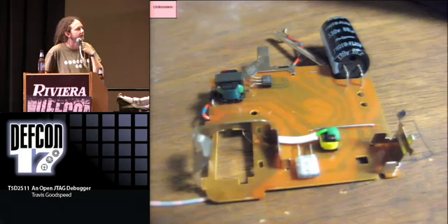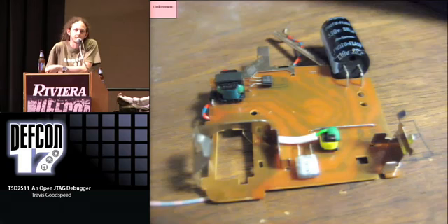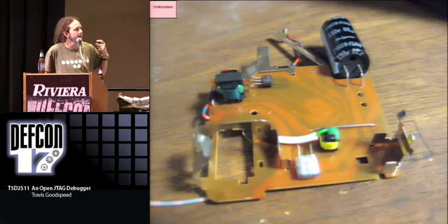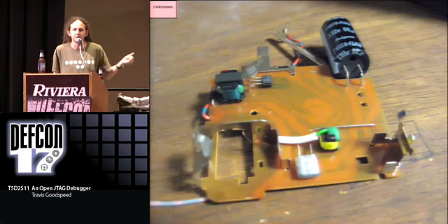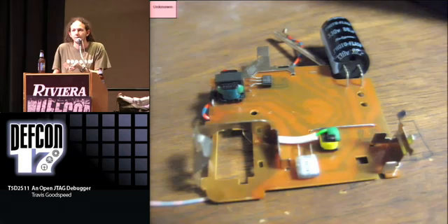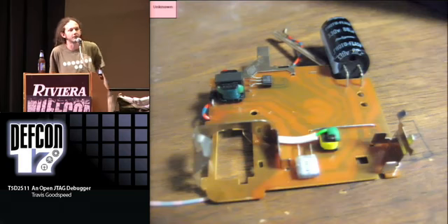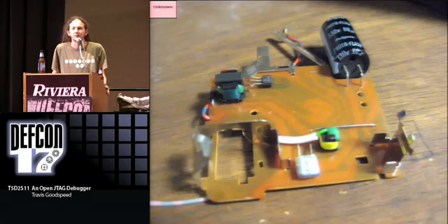But it stands to reason that if you could burn out the input and output pins of the JTAG state machine, then when an attacker tries to break into the chip through JTAG, he'll have no way to communicate with it. The Ember EM250 vulnerability that I presented at Black Hat recently could be fixed by this, because you can't connect to the chip externally once the pins are broken. In any case, sparks are going to fly, and this thing shocks like living hell.